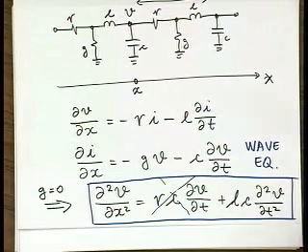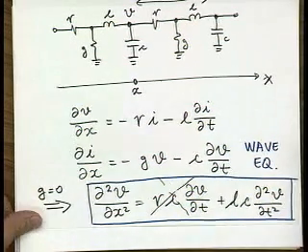So basically in the diffusion scenario for RC, you have just signal going from source to destination and gradually developing voltage at the final destination point. And over here you will have signals that are swinging back and forth, reflecting from the source, destination, and so on until it's finally settled.